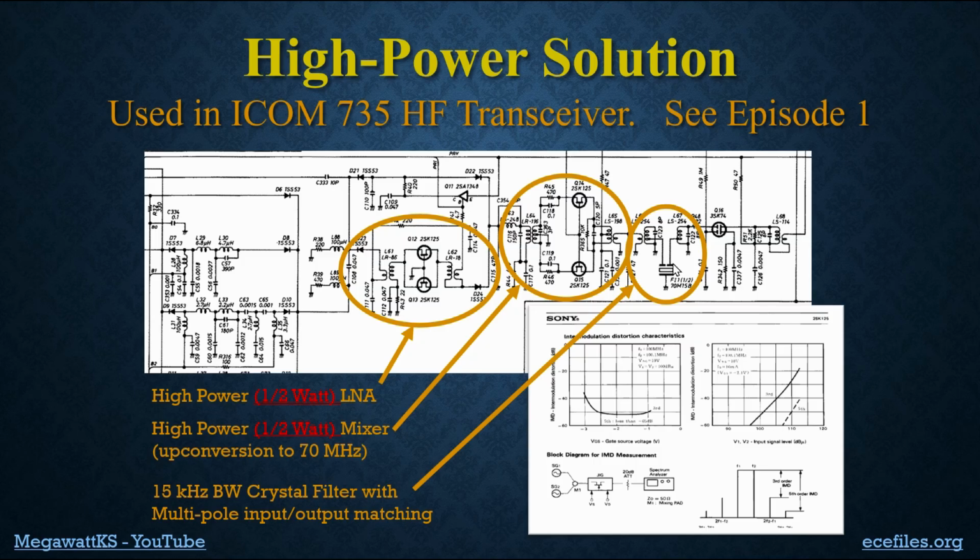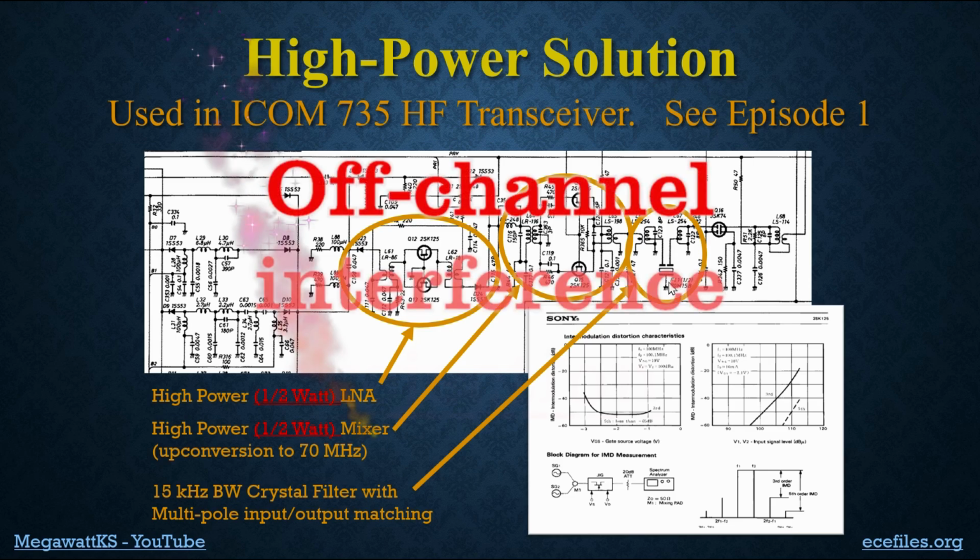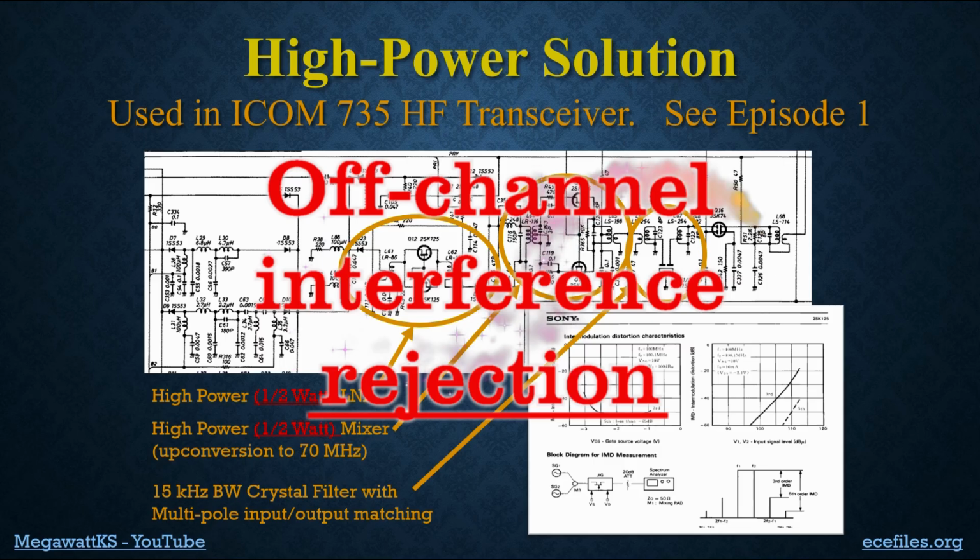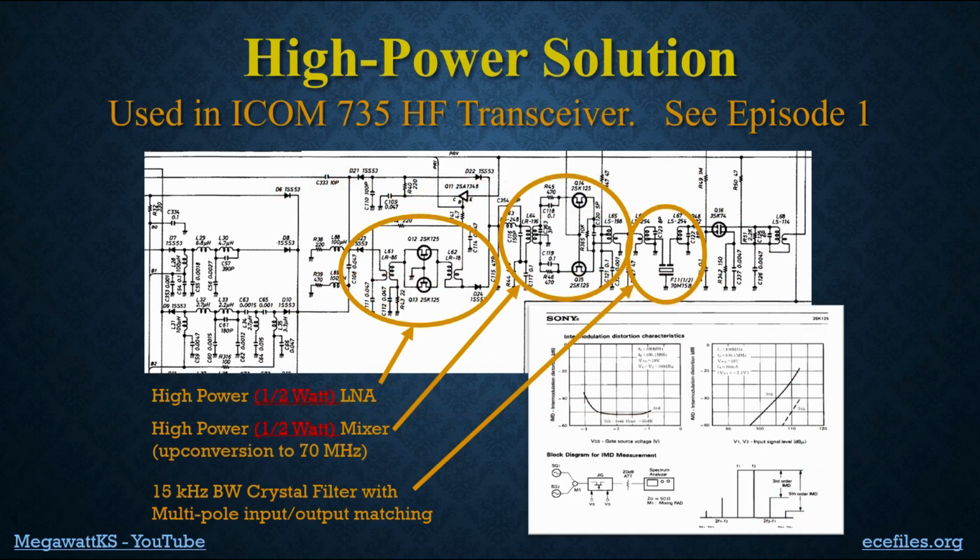Ordinarily, I'd want more than one, but it looks like they've got filtering here in this transformer and filtering here and filtering here. That provides the extra out-of-band interference rejection that you need when you're trying to make a radio receive with 100+ dB dynamic range. But that's a lot of power. That's 1 watt. How much would it gain you?